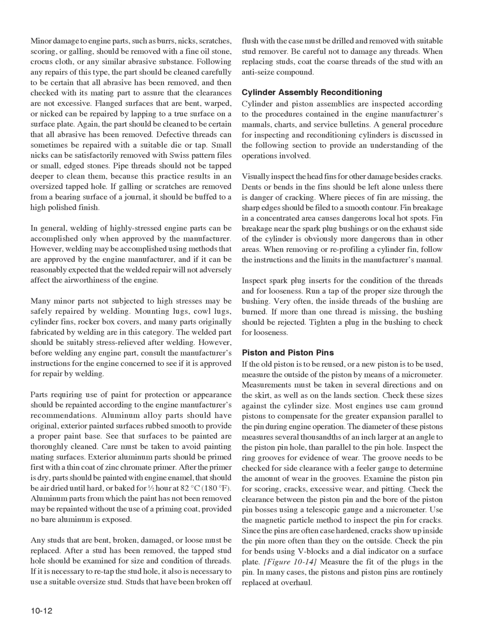Any studs that are bent, broken, damaged, or loose must be replaced. After a stud has been removed, the tapped stud hole should be examined for size and condition of threads. If it is necessary to retap the stud hole, it also is necessary to use a suitable oversized stud.